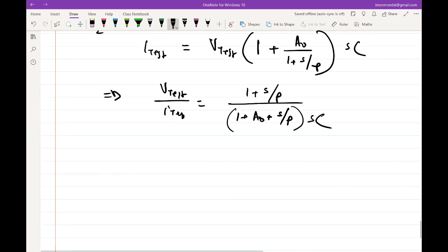So let's say you put together something and you get an impedance, some Z of S, where the value of Z of S is this, right? So this is a frequency dependent element or a combination of elements. I can break it down into frequency dependent capacitance, inductance, resistance, and all. I can do that, but it doesn't give much intuition, right?